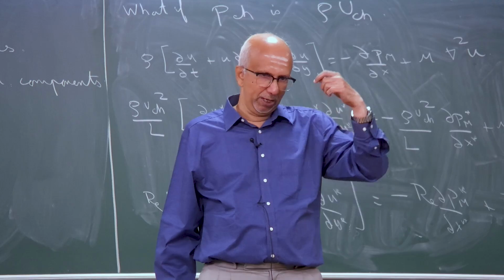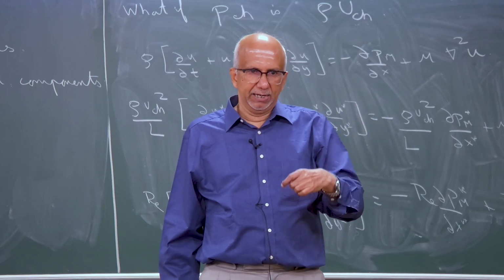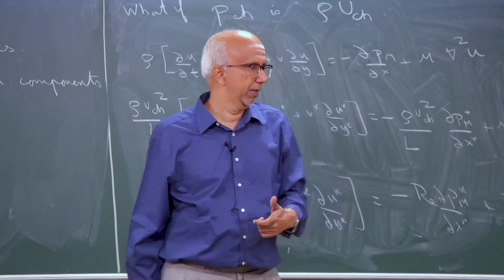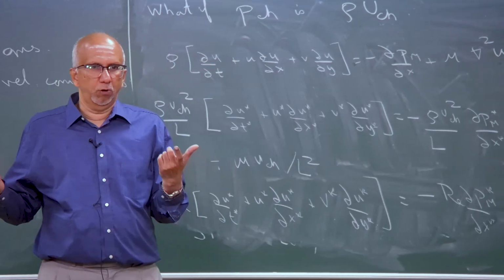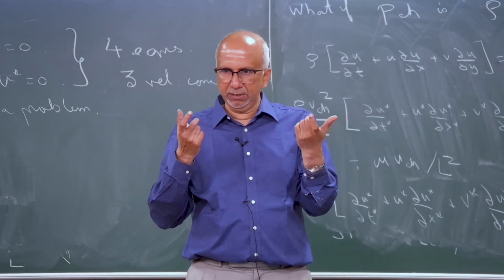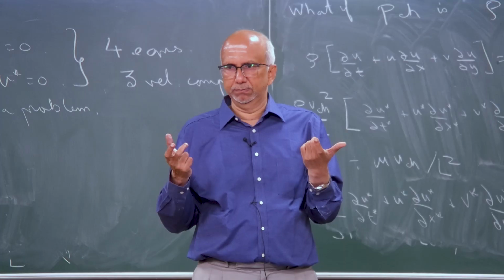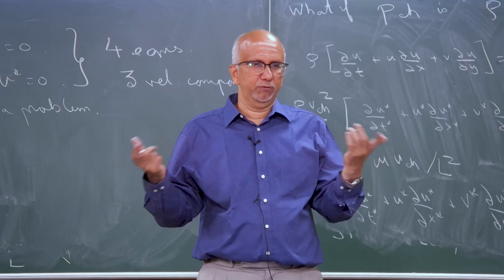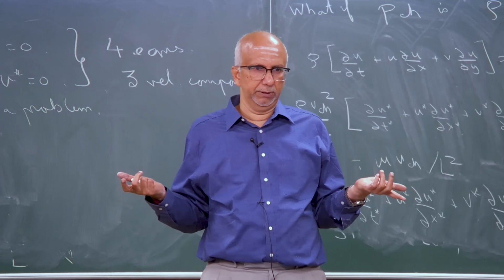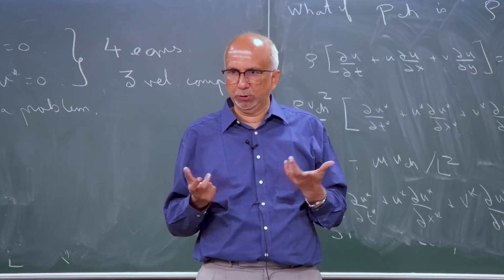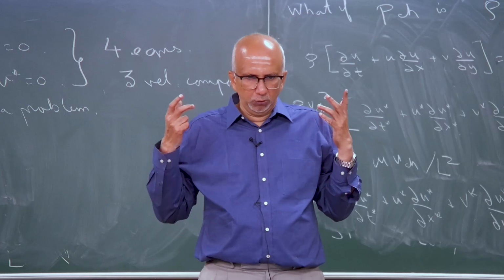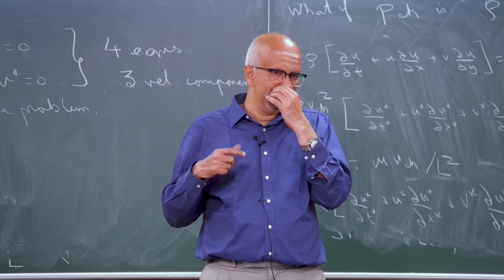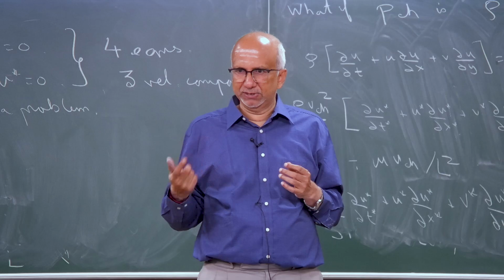You have to try different combinations and see which one makes sense. In the earlier scaling, we said pressure forces and viscous forces are balancing. Here in this new scaling, the viscous forces are equal to 0, nothing to balance the viscous force, nothing to drive the flow. So you have to think of the problem both mathematically and physically when doing dimensionless analysis.